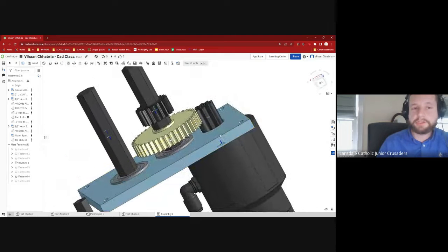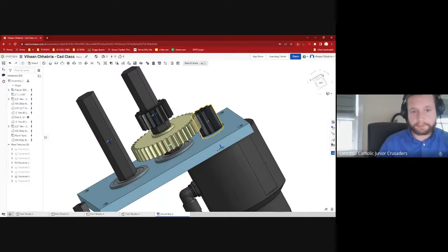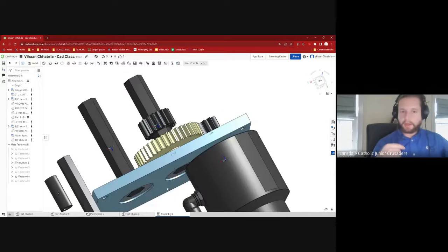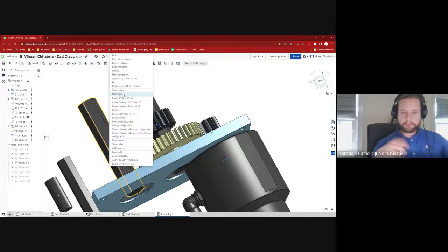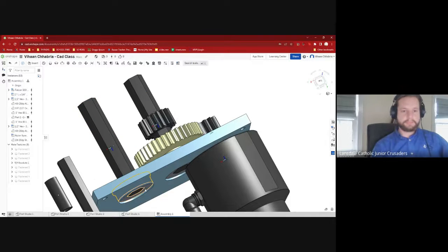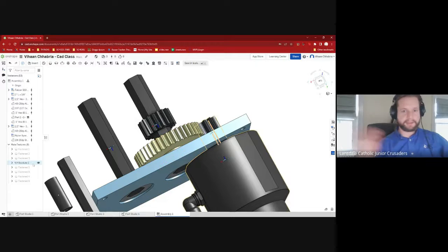Make sure you change your layout sketch in your 2D part, right? Yeah, I already changed that. Okay, good. As long as you change that, you should be good. This is the part of design where you can go back and forth. You can very easily put in different gears and different center spacings and see what works with the gear train. That's the very iterative part of gear train design. Especially in CAD, it's very easy to go back and forth and change things right now, much more easily than later when you build the thing.